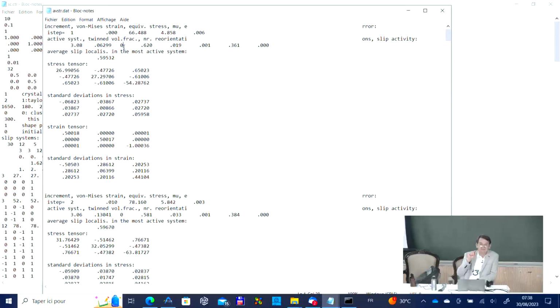And then we put volumes progressively into each variant in each increment of the calculation. Their volume is increasing, and they are part of the polycrystal. So certain variants which are active, those grains will increase in volume. There is no artificial switching of one grain suddenly replaced at a given strain with one variant, you know. No such thing.